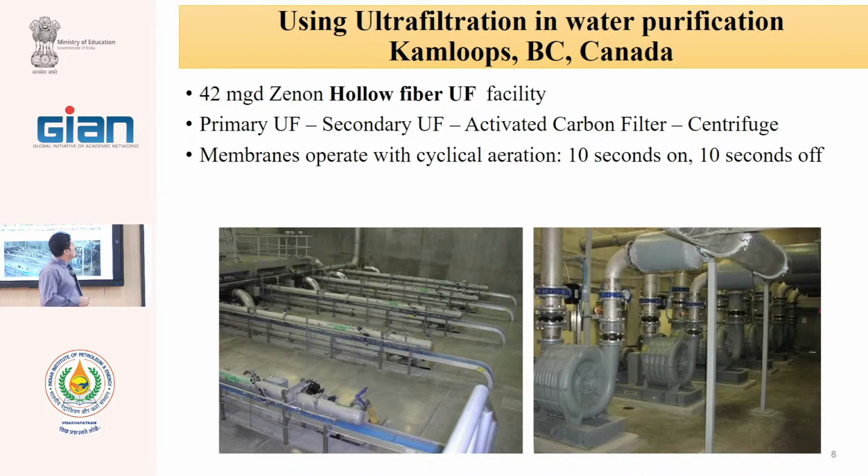For this process, two parallel UFs are used. The primary UF is about 100,000 Dalton, and the secondary is 50,000 Dalton molecular weight cutoff. And after the final, they use the activated carbon.